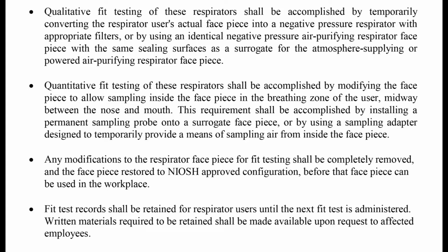Quantitative fit testing of these respirators shall be accomplished by modifying the facepiece to allow sampling inside the facepiece in the breathing zone of the user, midway between the nose and the mouth. This requirement shall be accomplished by installing a permanent sampling probe onto a surrogate facepiece or by using a sampling adapter designed to temporarily provide a means of sampling air from inside the facepiece. Any modifications to the respirator facepiece for fit testing shall be completely removed and the facepiece restored to NIOSH approved configuration before that facepiece can be used in the workplace.